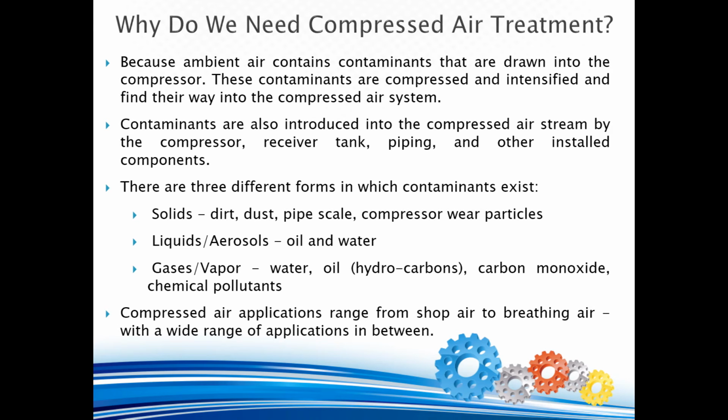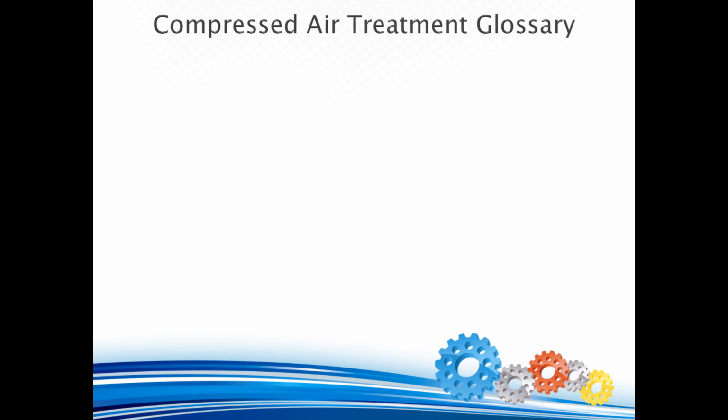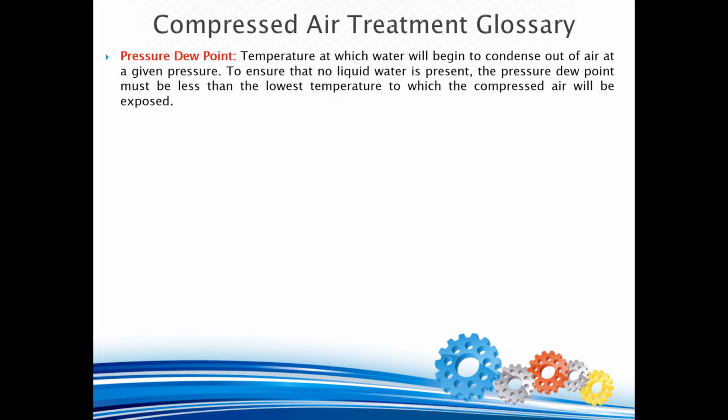Compressed air applications range from shop air to breathing air, with a wide range of applications in between. Let's review some key terms via this compressed air treatment glossary. Pressure dew point: the temperature at which water will begin to condense out of air at a given pressure. To ensure that no liquid water is present, the pressure dew point must be less than the lowest temperature to which the compressed air will be exposed.